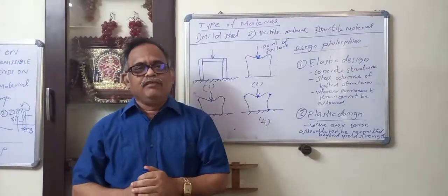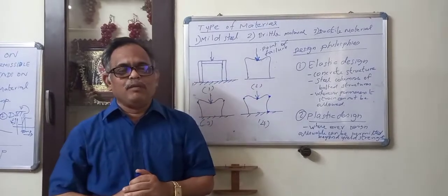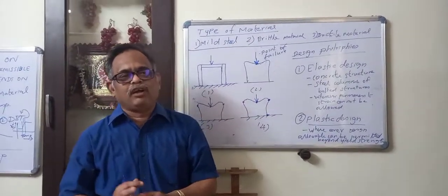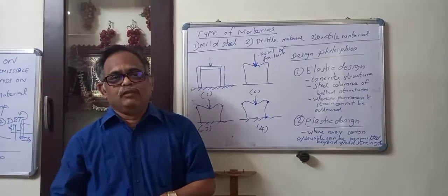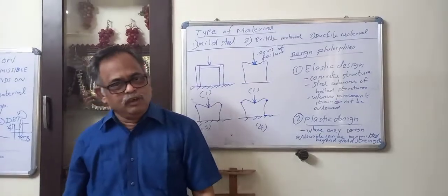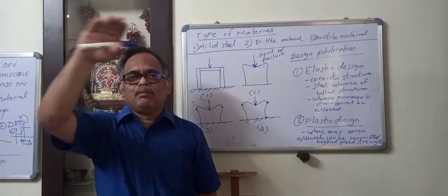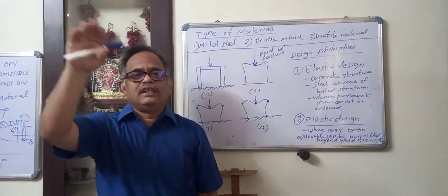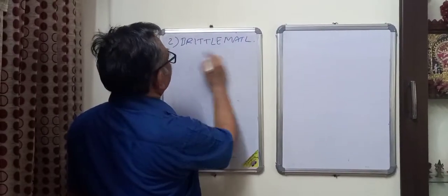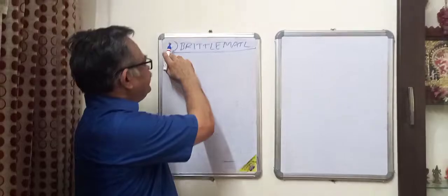be selected below the elastic limit, or the proportional limit. And if deformation is permissible for those applications, for cheaper, less serious systems, we can always go in for plastic design, where we select the maximum permissible stress less than the ultimate tensile strength. That's all. Okay, now we'll see the second case.